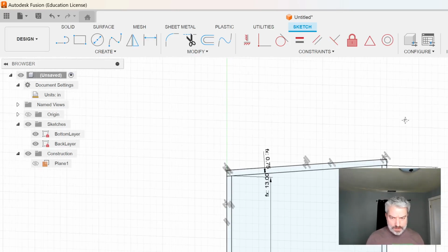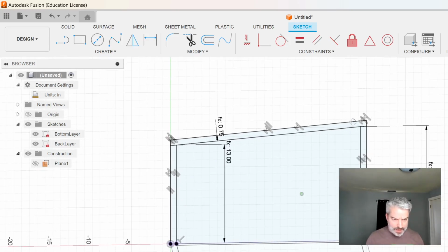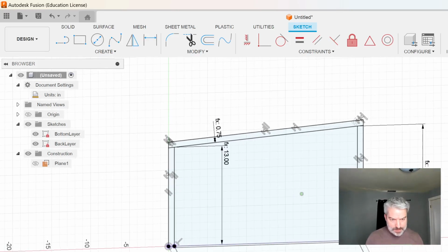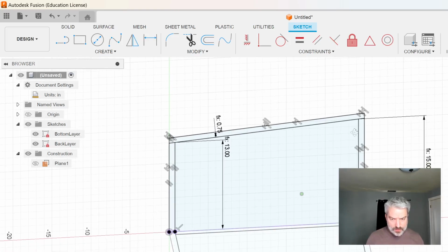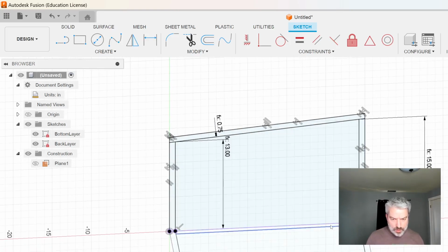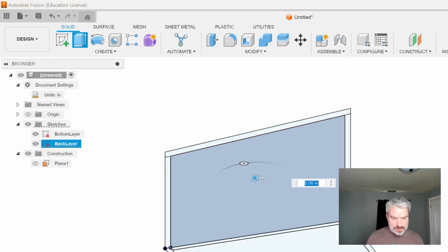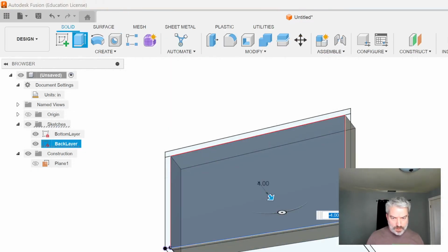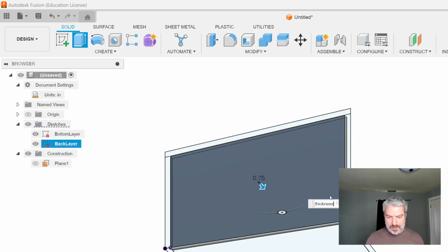What I want to do is, let's see, we can start at the bottom. Is this going to matter? I am going to extrude this one up. Let's start with this piece actually. This is going to be my wall, and I'm going to extrude it this way. I can see it's minus, so I need to do minus wood thickness. Now, as I do that, I'm very tempted to hit enter twice. Oh, in this case, it's not going to matter since it's the first thing I'm building.